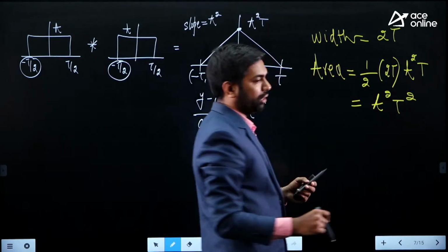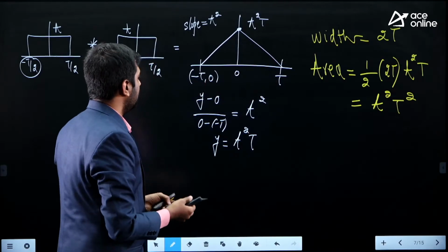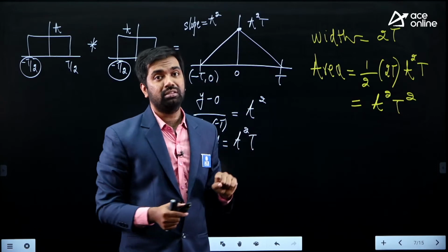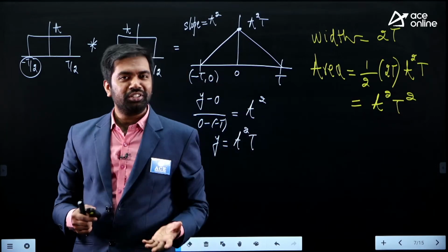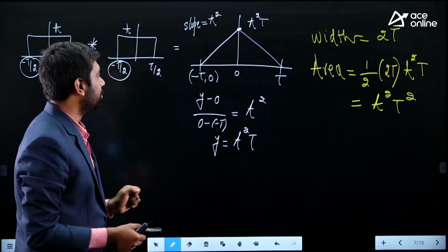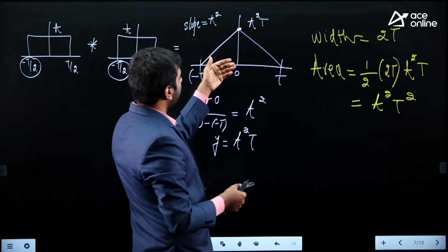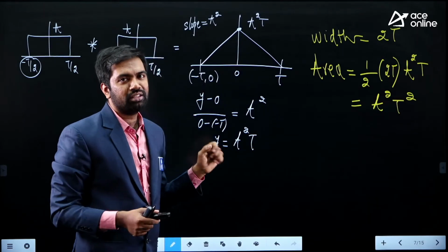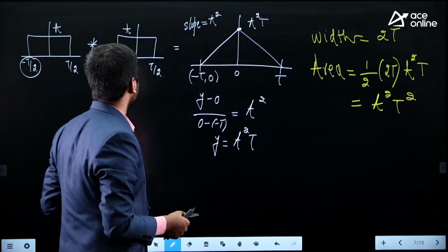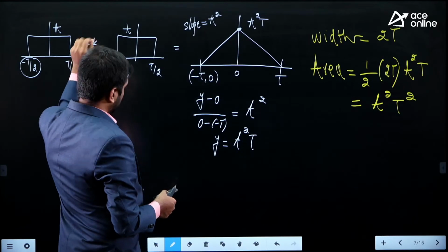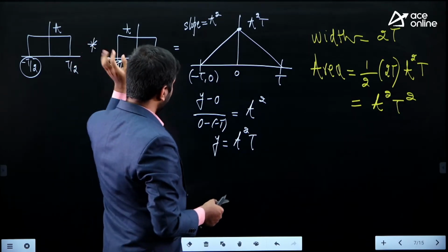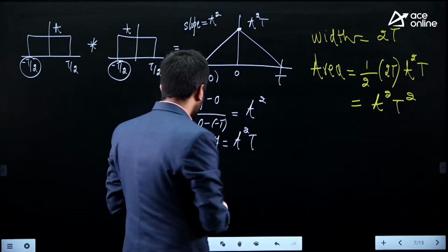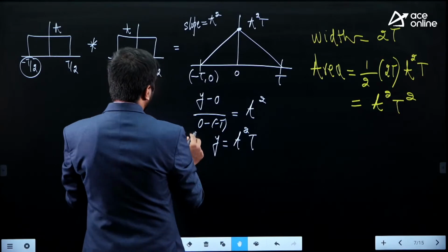So these observations are important. I'll tell you why. Actually, the focus is about the Fourier transform of a triangular pulse. I'm trying to find the Fourier transform of this using the rectangular pulses. Convolution in time leads to multiplication in frequency. Okay, convolution in time leads to what? Multiplication in the other domain.